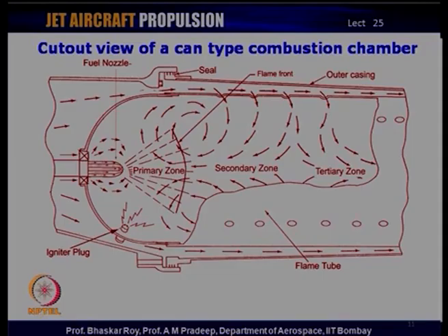These swirlers give a huge swirling motion to the flow, and then we have some kind of a bluff body over here, which creates more swirling flow and more local vortices. These vortices essentially create a huge recirculation around this zone, as we discussed in the last class. And this recirculation zone essentially aids the process of evaporation and mixing.